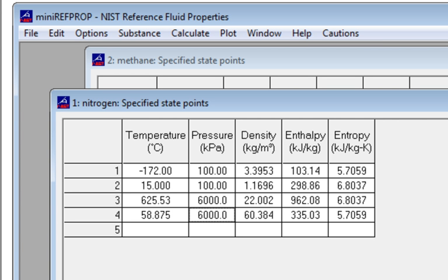It comes out at 15 degrees C. Did I say 15 or 25? No, it comes out at 15. I said 15 and 100. And that's the entropy. And then what I did was I said isentropic compression to the pressure of 6,000. That coughed out the temperature of 625 degrees C. So I didn't use the constant K, but that's an estimate.